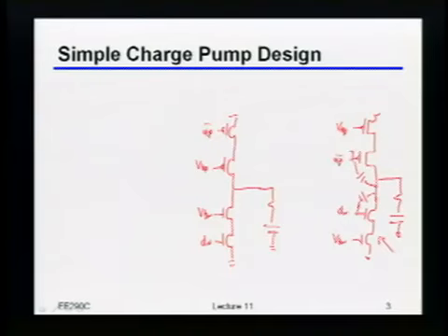So what will happen is you'll just get some straight capacitive coupling directly to the output, right? Now, maybe that's not too bad. Maybe you can make that ratio sufficiently good, meaning that you can make the loop filter cap substantially larger than that coupling cap from the switch. But if you flip things over, it's not that the problem completely goes away, but now at least you have a little bit of isolation or a little bit of extra divider that comes into the picture.